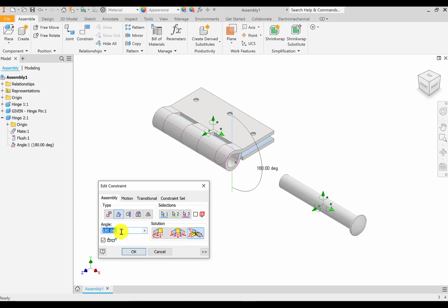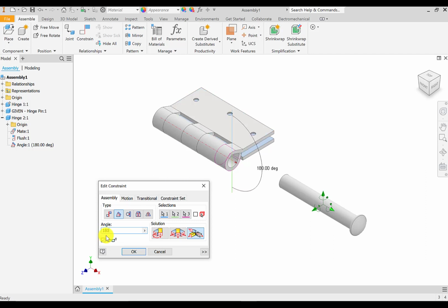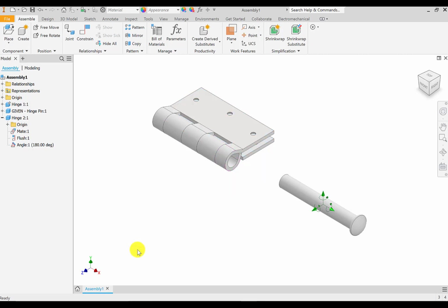As we saw, we can manually set the angle between the two brackets, so we can control if we want the hinge to be fully open, fully shut, or somewhere in between. This is practical because we might want our assembly model to show the extent to which our door hinge assembly can open or close. After making this angle constraint, 0 degrees of freedom remain with the hinges, but our hinge pin still needs to be constrained.